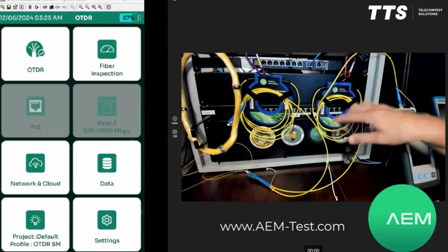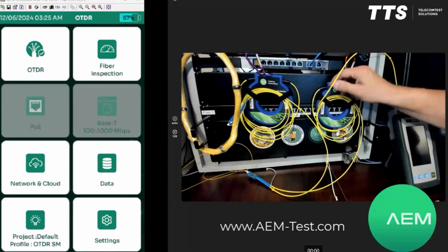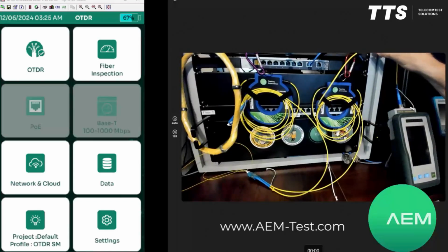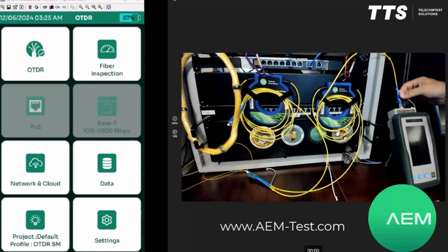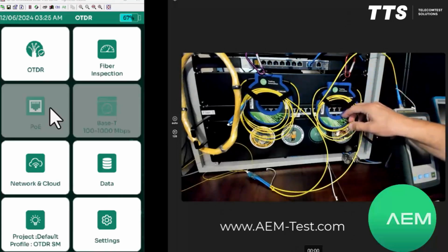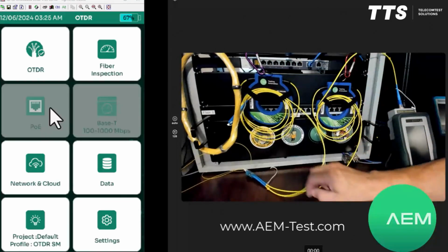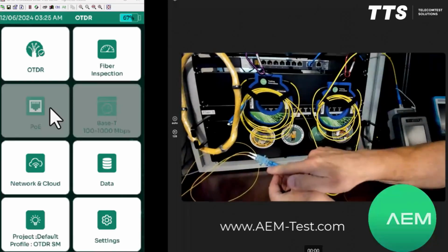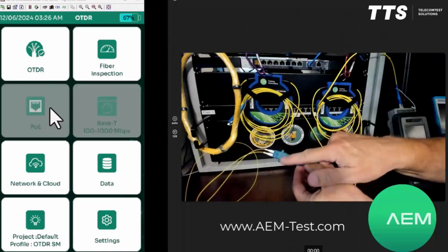So what I've got here, this launch cord right here, we can see this fiber comes over here. I've got it just hanging up here in a distribution ring to act as a strain relief. It comes down and it connects to my OTDR adapter on my TestPro. Now the screen's dark because I'm using VNC. That's a computer connection to my tester, and we see the display on the left here. So that is one end of my launch cord. The other end of my launch cord with the LC comes down here, and it is connected right here on this cord. We've got an LC coupler here.